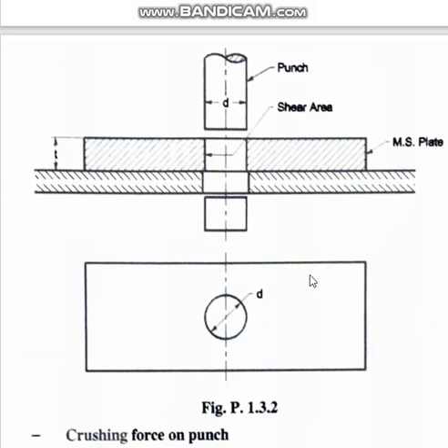A plate is there. In the middle of that, a hole is to be made. How will you make this hole? This is that plate. Now what is this down one? This down one is a table on which this plate is kept, and that also has a hole because the punched piece should fall off. That's why.